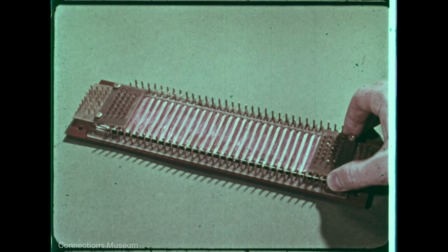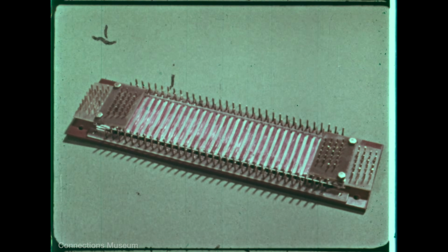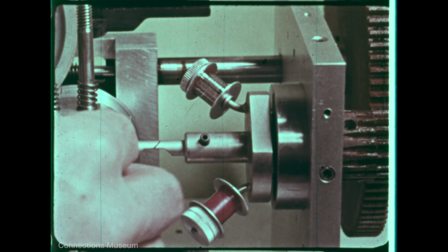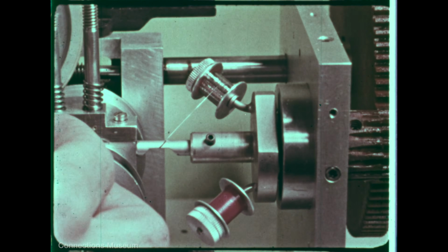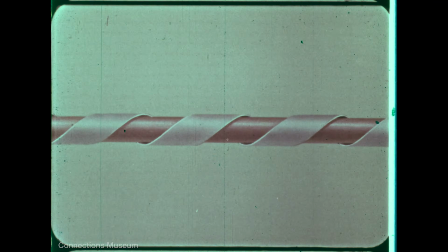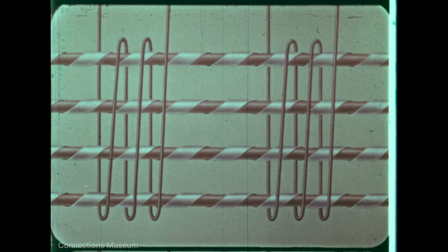Magnetic storage is also the principle underlying the twister memory. The twister gets its name from this ribbon of magnetic material, which is wrapped 100 turns per inch around an insulated copper wire. The ribbon is only about 1/3 of a mil thick, and the wire has a diameter of less than 3/1000ths of an inch. In this particular memory, 26 twister wires are embedded in a plastic sheet and mounted in a frame so as to pass through 32 solenoids.